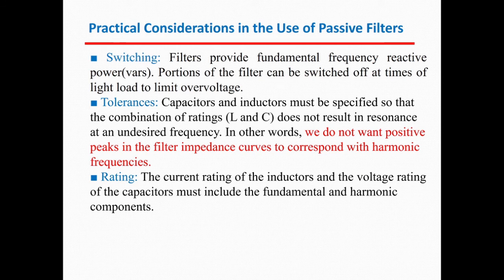Rating. The current rating of the inductor and the voltage rating of the capacitor must include both fundamental and harmonic components. Okay, so again, when we select or design the system, we have to consider not only the fundamental, not only the harmonic, but both.